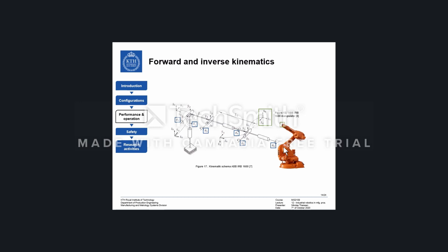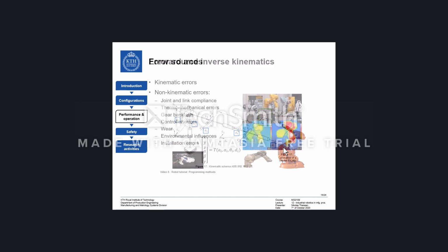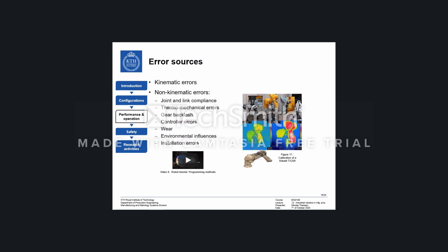So thinking, where is it in terms of position, x, y, and z, and in terms of its orientation, which is usually represented using Euler angles and quaternions. And in order to do that, one uses a transformation which is dependent on the Denavit-Hartenberg parameters. And these parameters also need to accommodate errors of industrial manipulators if you want the accuracy to be very close to the repeatability.